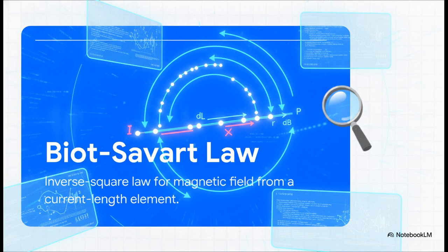The magnetic field relies entirely on a cross product between the direction of the current and the vector pointing to wherever you're measuring from. Simply put, magnetic fields operate in true 3D space. They act perpendicular to both the current and the distance. Because of this specific geometry, if you stand so that a current flows directly toward you or directly away from you, the magnetic field you observe is literally zero. You only catch that field at its maximum when you're looking at the wire from a perfectly perpendicular angle.